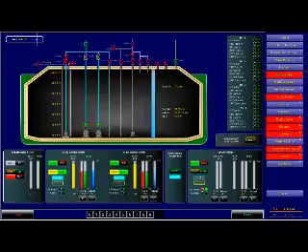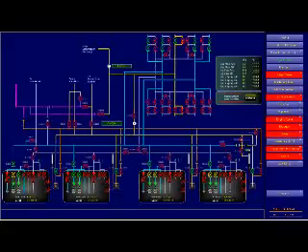Watch that, now your alarm has gone on the 97%. So now you're happily discharging. Just watch for the pressures in the tank, the atmospheric tank pressure. Never let the tank pressure go in minus. If you do not get vapor enough, ask the shore to supply you more vapor. I will tell you from the terminal side how much you are giving me. And it should always be positive.